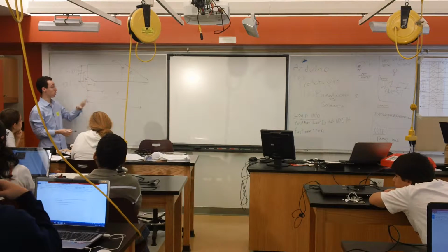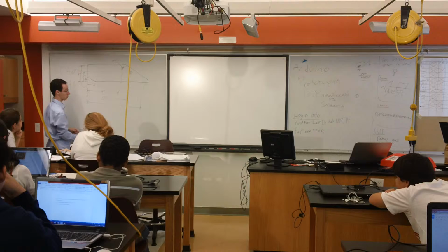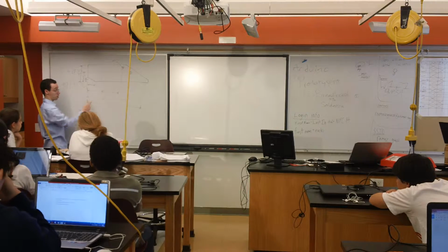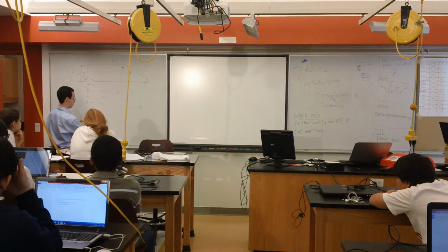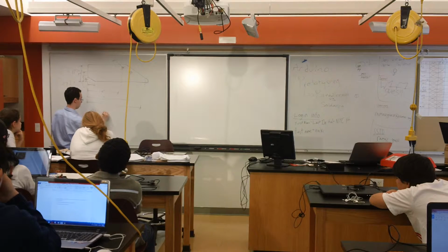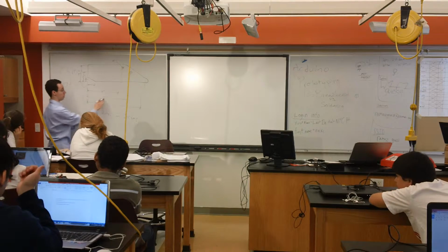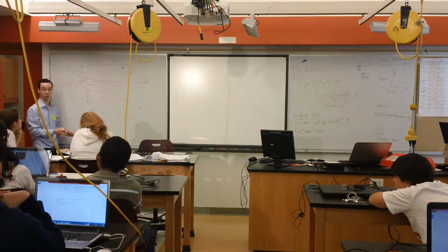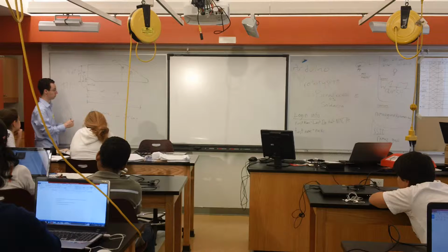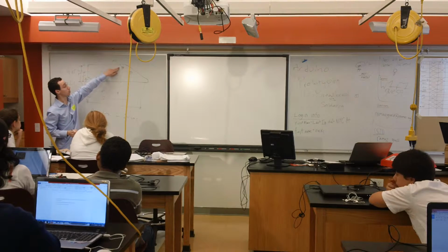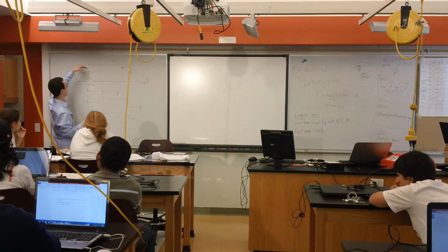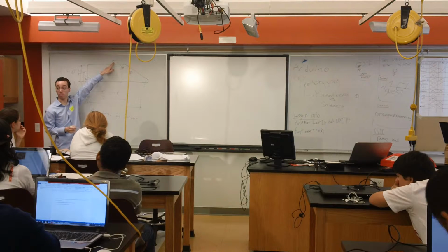Also, when you're doing a lot of dimensions like this, it's common to say, instead of having the inch symbol on everything, I could go like "all dimensions in inches" or millimeters or whatever I'm doing, and then I would just not have that symbol there, just to keep things simple. Anyway, so I specify where this hole is now, and I specify what diameter it is.